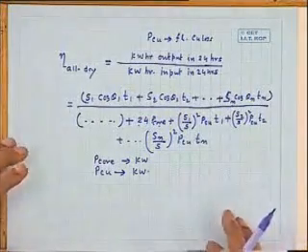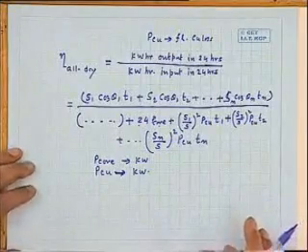So it is the energy efficiency which should be judged, or the value of which should be seen, when you purchase a distribution transformer, rather than its ordinary efficiency. Because in case of a distribution transformer, the primary remains energized for 24 hours. So that power loss 24 into P core, particularly during no load operation, just goes as waste.